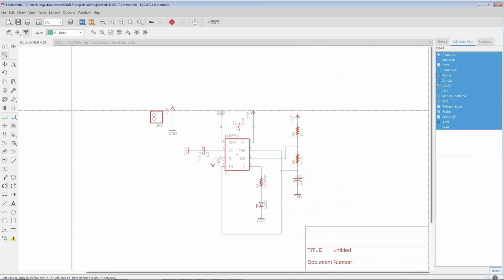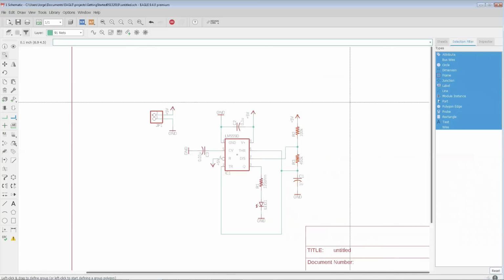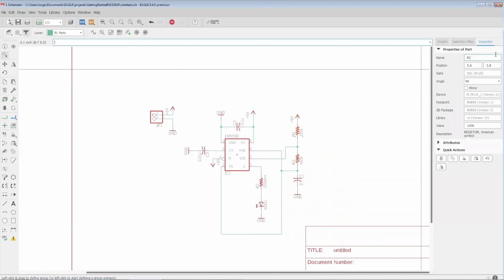It's possible to change to just select a single component and use the inspector to change the properties, like you were setting up the values in the way that you did it with the value command. It's possible to have it done by selecting that part by itself, as he just did, and then right there you have a value which you could have done right there as well. Yep. Actually, that's the way I prefer to do it. To be honest with you, I prefer using the inspector and just go part by part. And that's how I use the inspector to change properties on my components. I use it heavily in the library as well. Extremely powerful. As you can see, you have all the quick actions that you can do on the object as well.